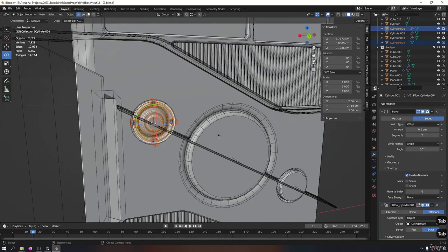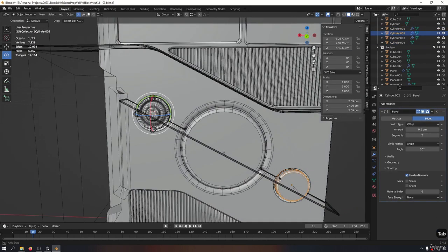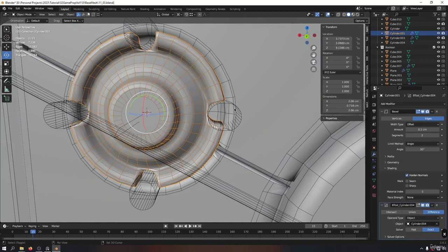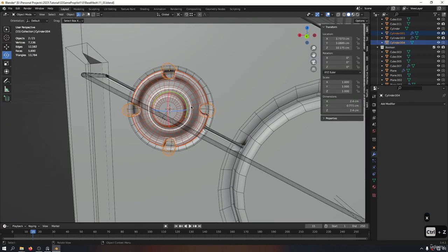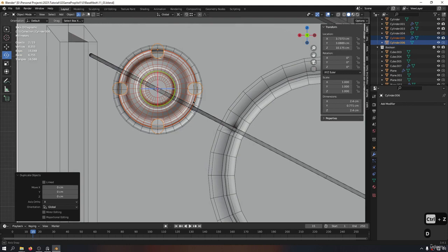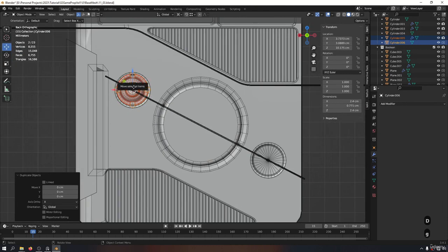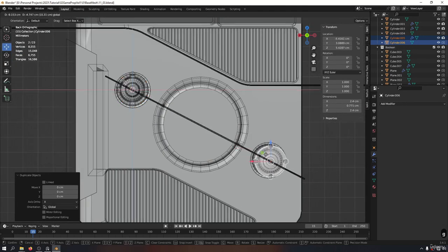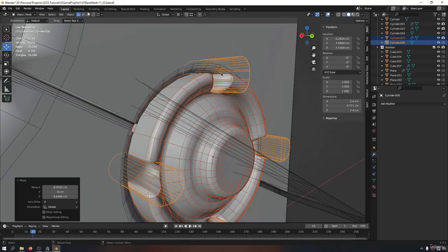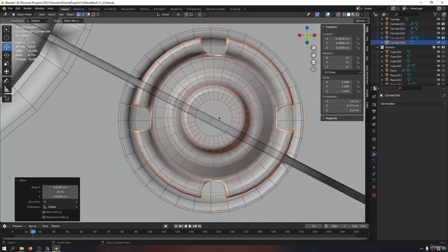So now I'm going to copy this one in here. Let's take this, remove it, take this one and the Boolean piece, Shift D, because these need to move alongside each other. Okay, and I'm bringing that to here. And make sure that you copy the object and the Boolean piece at the same time.